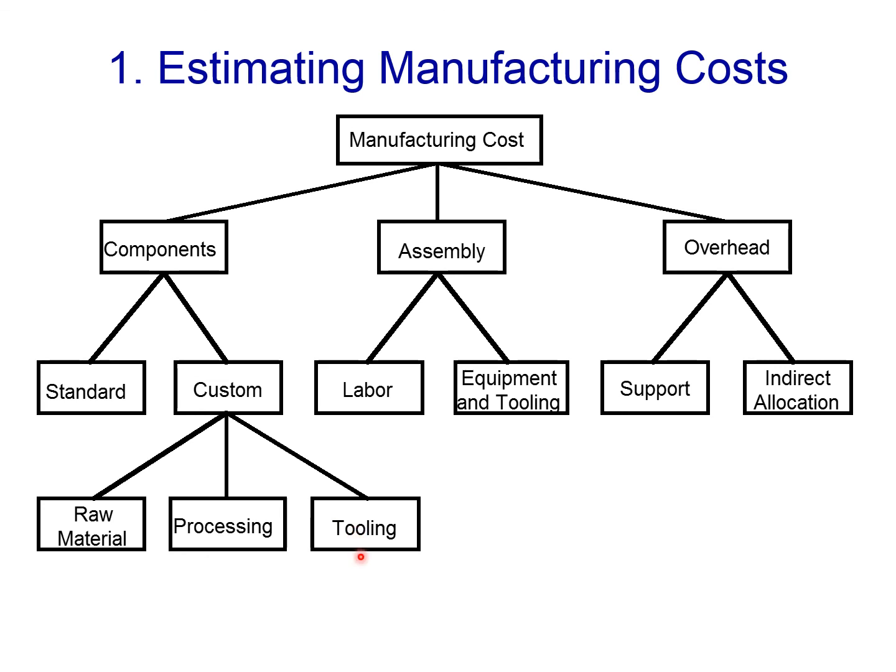Then the tooling cost, which can be estimated as follows. Tooling costs such as molds, dies, and fixtures. The unit tooling cost is simply the cost of tooling divided by the number of units to be made over the lifetime of the tool. Appendix B at the end of the book chapter also has some approximate tooling costs for a variety of shapes and parts.